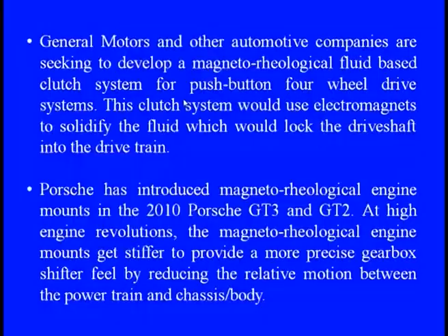So, whatever the operating or boundary conditions are changing, they can be immediately adopted and responded to in a corresponding way. That is why wherever we require such applications, from automobile to aerospace to helicopter dampers, or even for the military, or where human responses are required more, the MR damper can be straightaway embedded into the system, and we can get such things.